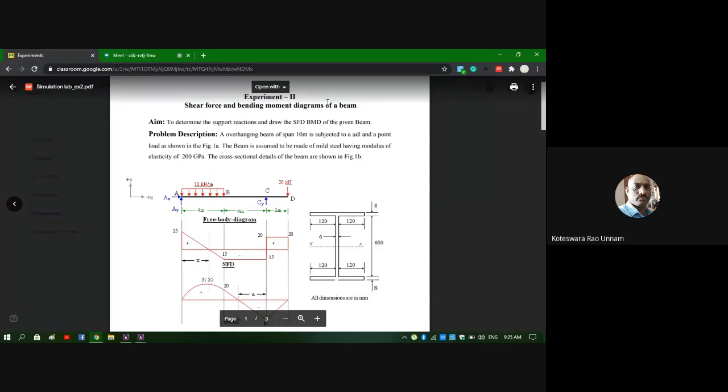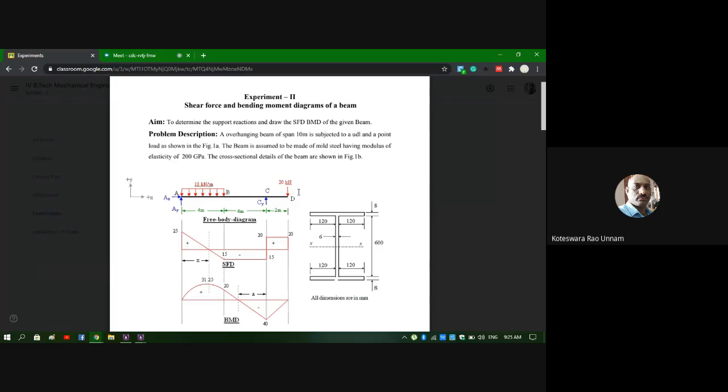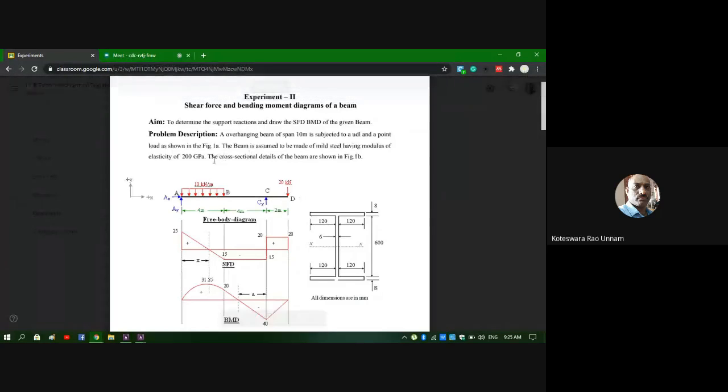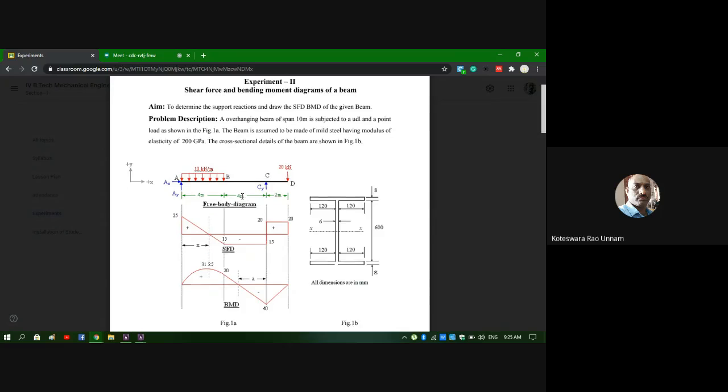The name itself suggests that it is a beam. So here the structure is a beam. That means the element we took in the earlier problem, the first experiment, that is a bar problem, an axial load problem. If you read that element description, that element can support only axial loads. But here you have transverse loads. So you cannot take the same element for this one. Now we need to take a separate element for this analysis, and that element we are going to use is BEAM188.